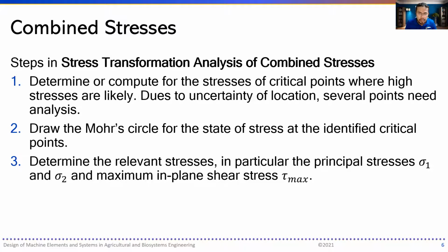Because on the surface, if they were members in equilibrium, so they're not moving, then, well, statics, not in equilibrium, because there could be a body that is moving that is in equilibrium. I'm sorry for that. So you have your bodies in static equilibrium. So these principal stresses and maximum in-plane shear stresses could be of less importance. But in bodies that are moving, particularly in machines or machinery, these are very critical.